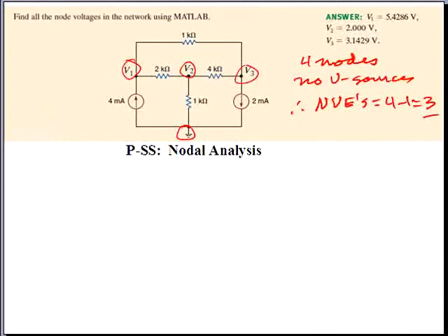As you recall, nodal analysis involves the use of Kirchhoff's current law at nodes, summing the currents, and solving that set of simultaneous equations. So first we'll label the positive current directions assumed at each of these nodes, which will enable us to write the proper Kirchhoff's current law for each one.